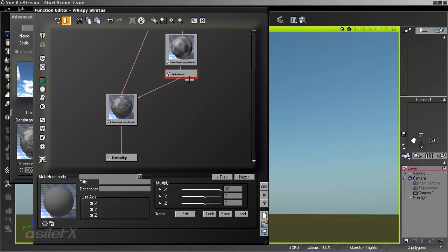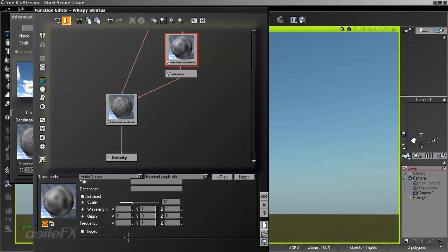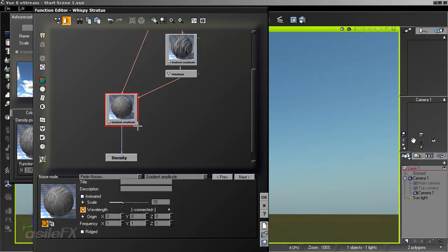So this way we've created our own custom turbulence, and it can end up being a lot more powerful than some of the other nodes. Using just the standard turbulence nodes, you'd have to match up all the different values, and it may not return the same output. So now we're basically stretching this noise around, really more intensifying the current setup. But what I want to do is take the frequency amount and increase it for the turbulence. And let's go ahead and do that on the y. I'm going to type in a value of 12. So on the y, we're going to have a lot more kind of curling.